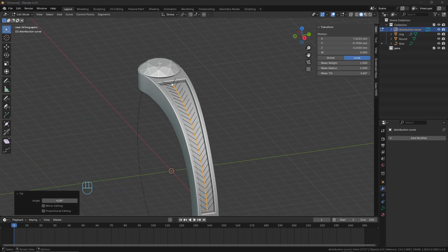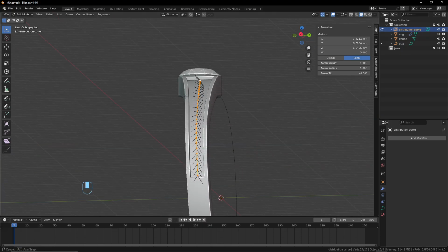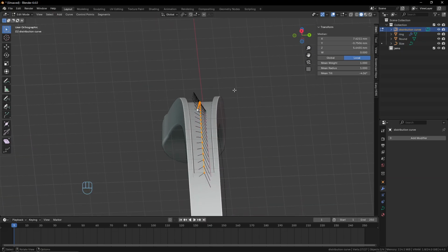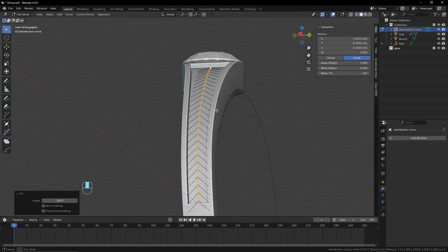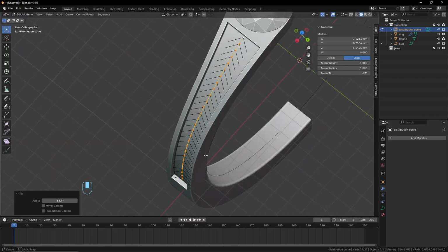And you can see that here it starts from here, you follow the lines, so here it starts here and it finishes here. Maybe I want to invert this in some cases, so in this case I go to segment and I switch the direction like that, okay. And maybe I come back again with a Control T to put everything back well oriented compared to the surface here.